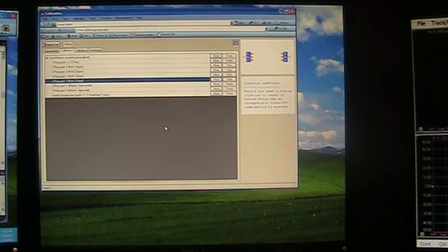It has all of the famous acronyms for calibration standards, standard techniques built in. You can use the ISSs that Cascade will sell you to go with the probes, or you can deselect that and put in your own coefficients, your own techniques. TRL, LRRM is a favorite of ours as well.